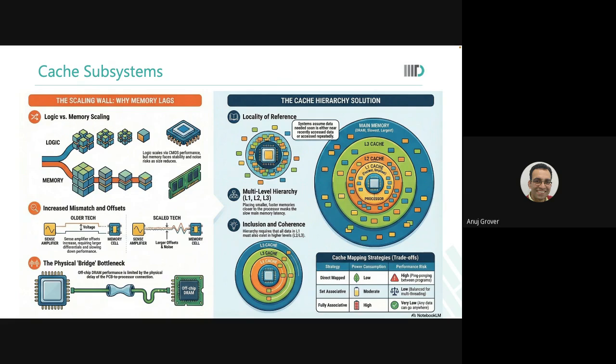There are so many figures of merit that need to be optimized, stabilized. We have sense amplifiers, which are analog in nature. Their offset requirement would probably increase with technology scaling instead of reducing with technology scaling. We talked about aspects like RC of word lines increasing, RC of bit lines also increasing. So with all these things coming into picture, memory performance can't scale.